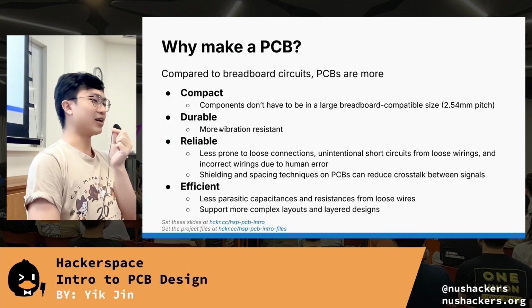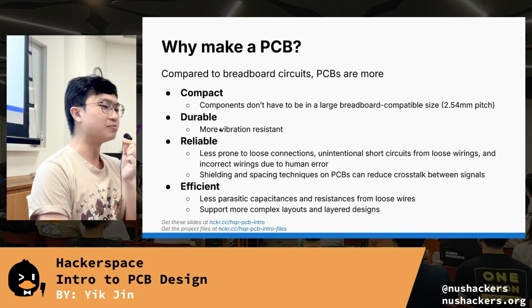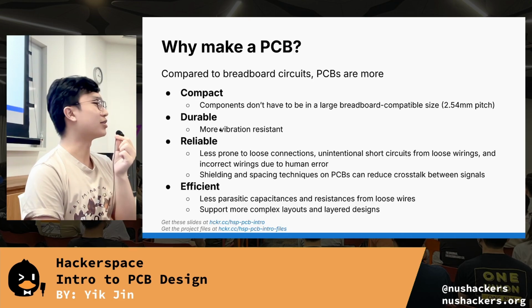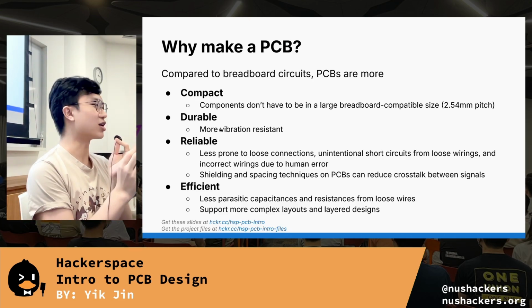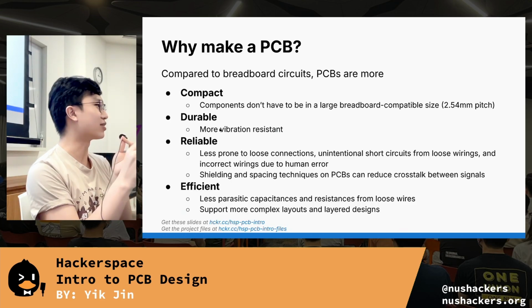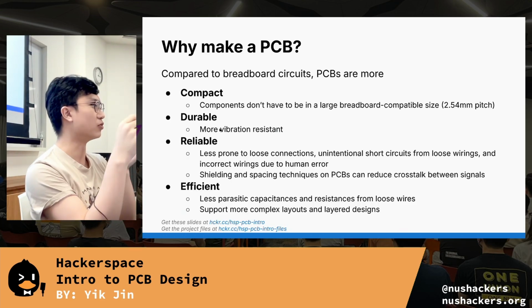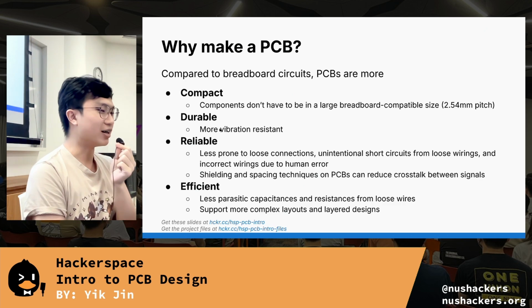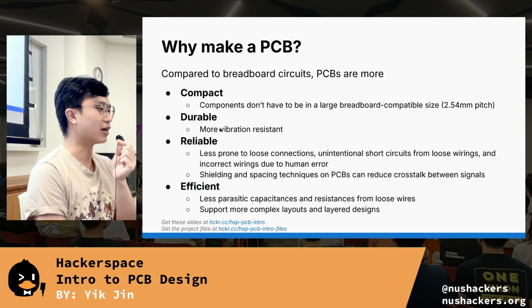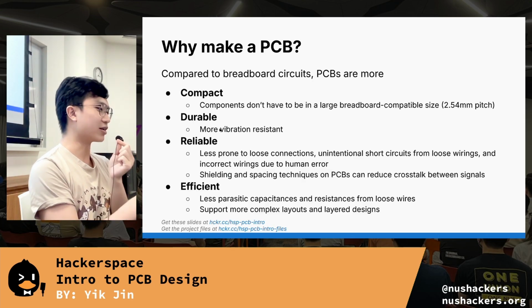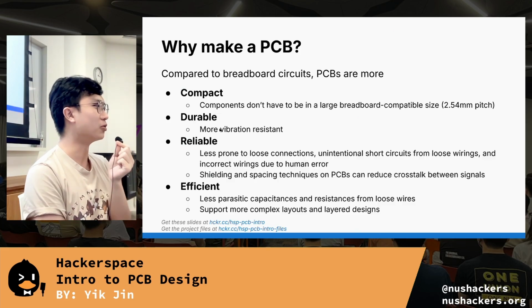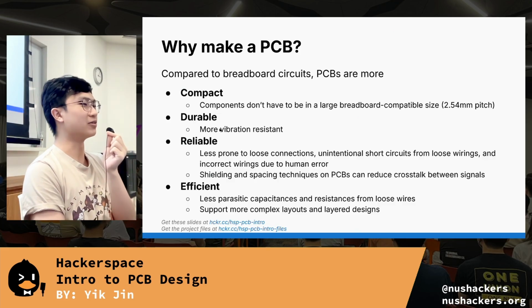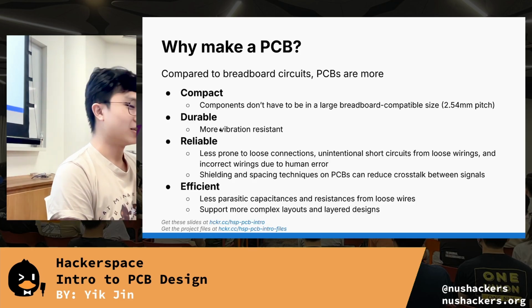On that note, it's also more reliable. You won't have issues like unintentional short circuits from loose wiring, like two wires accidentally touching each other outside the breadboard or even inside, sometimes if you stick them in at a wrong angle. Or you might have incorrect wirings if you use a breadboard. If you make your circuit and it works, and you take it out, then the next day you want to assemble it back, sometimes you plug it into the wrong hole. PCBs will not have that issue.